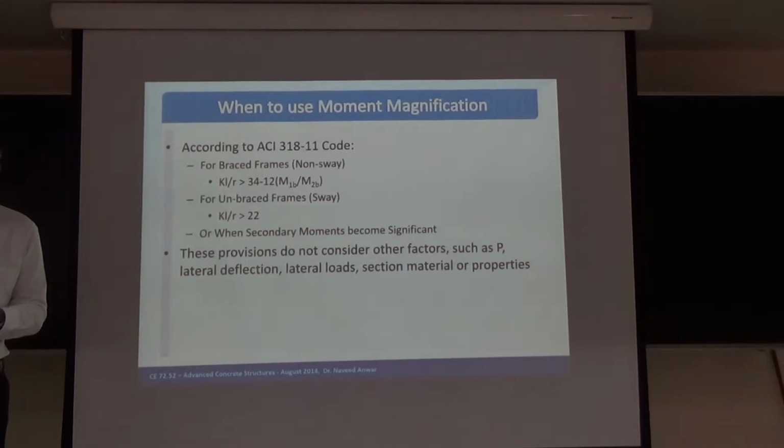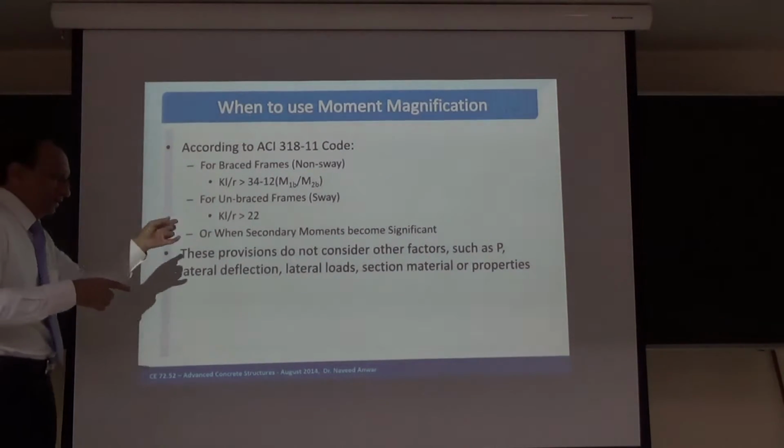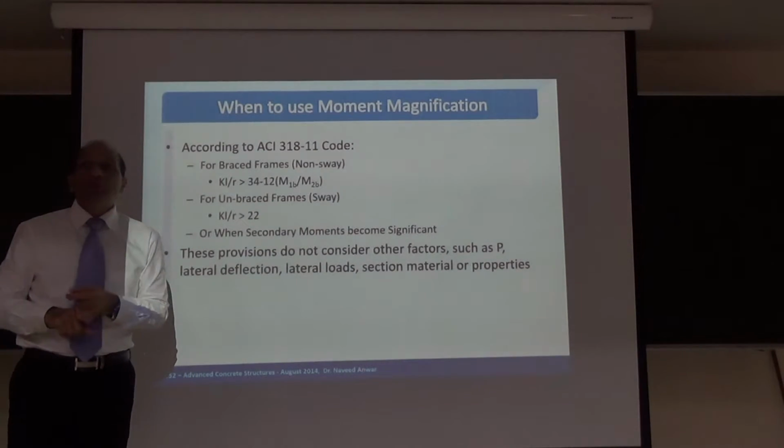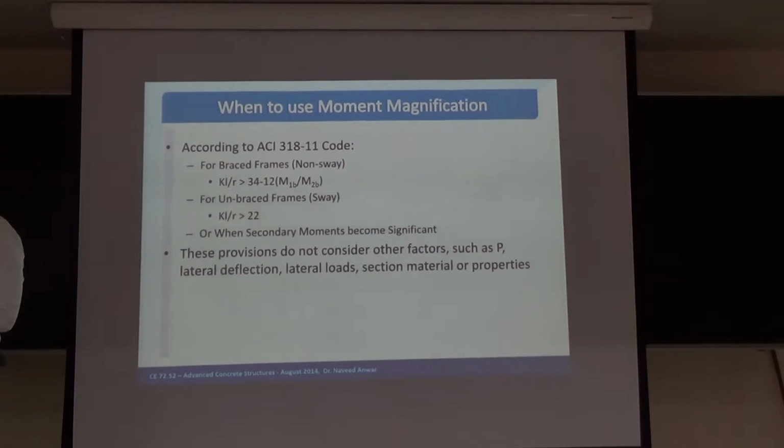Always 2-story buildings, 3-story buildings, they are the ones that get demolished most often because of these things. First of all, there are many other reasons, irregularity and so on, this is one, and people do not pay attention to them. So if you are going to be a structural engineer, do not underestimate a 2-story building, thinking, oh, it's a 2-story building, I don't need to care about that. That is the one that you need to care about much more than the tall building.